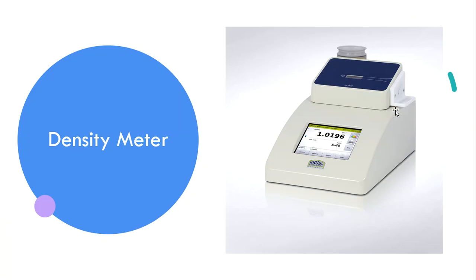Here is a very simplistic little density meter. These things can be as fancy as you want them to be, but this is just a laptop-size bench model, nothing connected to a computer, nothing connected to software. Just inject your liquid in there, and that liquid is going to be measured, and the density meter will pop out a number for density. It also will pop out a number for specific gravity, but density is one of those things that it's definitely going to do and provide to you. The USP monograph also says that we have to do this 5 times, so there's a little bit of statistics involved there.